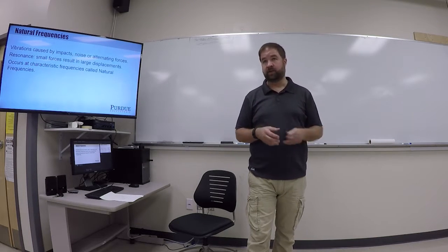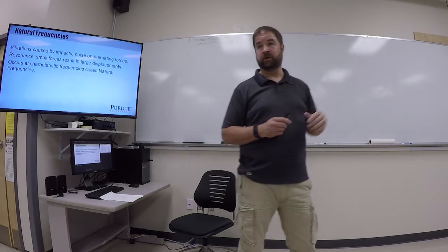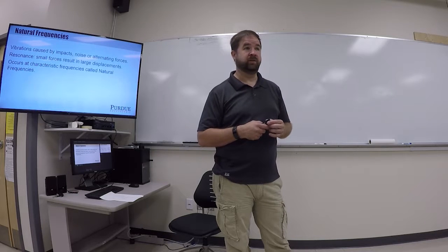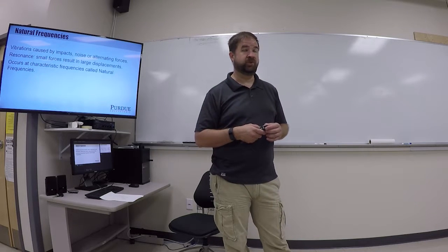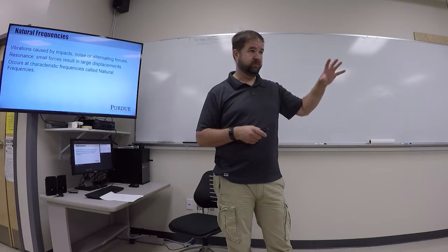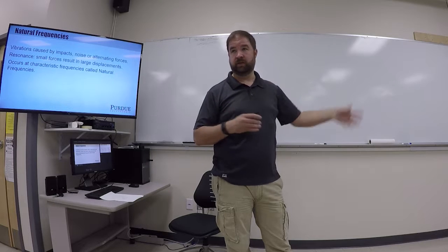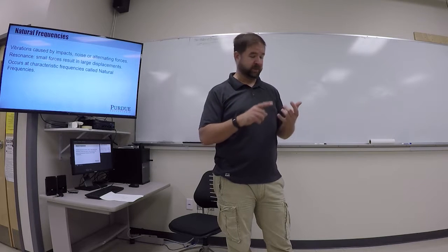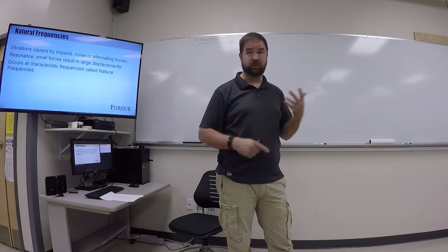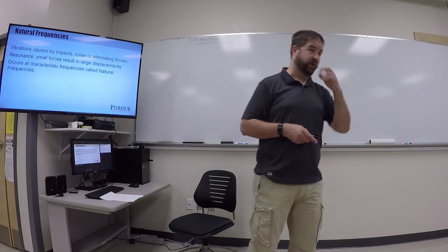Another really common thing is we put equipment in a building on the second floor or third floor, and civil engineers typically don't check natural frequencies of buildings for vibrations from industrial equipment. That's not something that generally comes into the code. They check stuff like earthquakes and wind loads and snow loads and all those kinds of things, but they typically don't worry about vibrations.